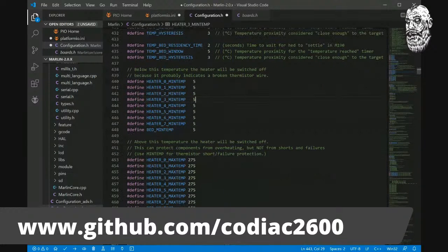So our next section is how low do we want to allow our printer to get before you get a min temp error. I run my printers in a very cold basement. Typically it gets to about 15 C in the middle of the night in the winter. So on my normal Prusas, I'd get an error. I'd wake up and it says min temp. You're like, why do I have a min temp? My printer's been off. Well, that just means you hit Marlin's suggested minimal temp before working correctly.